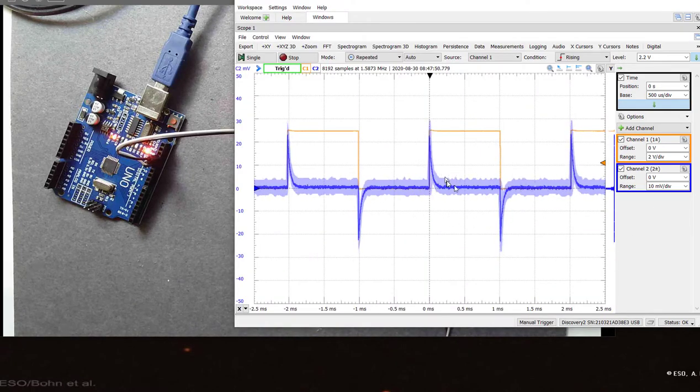This voltage noise that we're seeing here is going to be present whenever we have a high impedance on channel 2 and we're looking at an aggressor signal on channel 1. There's fundamentally nothing we can do about that. We just have to be aware of it. And so that says when we look at high impedance measurements on channel 2 and we have a high aggressor signal on channel 1, watch out, because we could have about 1% capacitive coupled noise on channel 2. That's one of the limitations of the 82 scope.